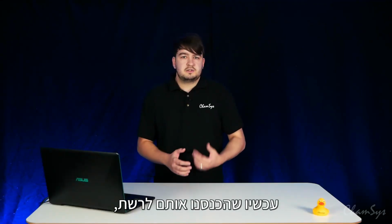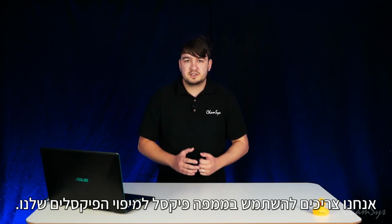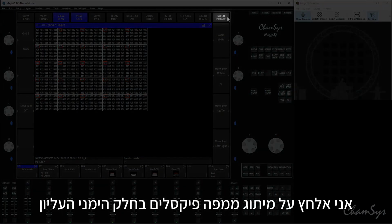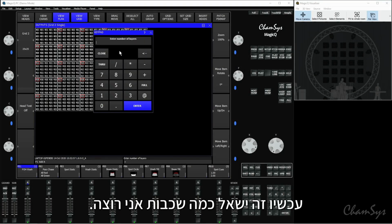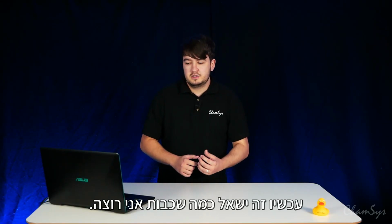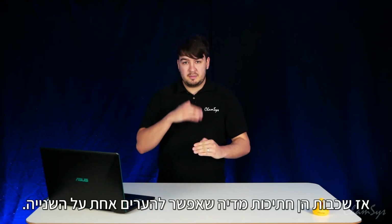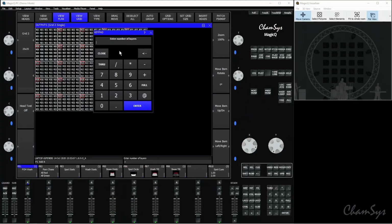So now that we've inserted those into the grid, what we need to do is patch a pixel mapper from that to use for our pixel mapping. So if I press Patch Pix Map up the top right here, I'm going to say yes, I want to patch that pixel mapper, and then it's going to ask for the number of layers I want. So a layer is essentially a piece of media that you can just layer up on top of each other. So I'm going to say I want 3 different layers.